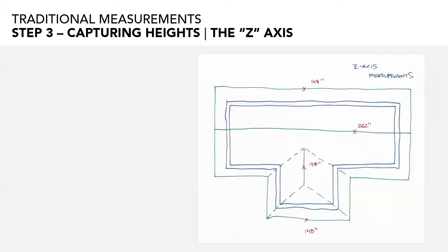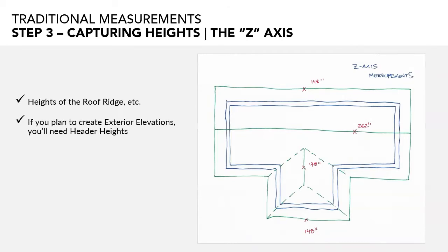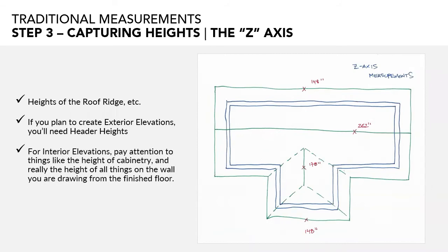And then plan on what you'll need to see in those exterior elevations and sections. Make sure you have either some basic height and good pitch information for your roof, or if it's safe to actually get up on the roof, gather as many heights as possible while you're up there. Make sure not to forget the heights of openings, such as windows and areas you plan to show, or the heights of items like wall sconces, for instance, if you plan to produce detailed interior elevations.